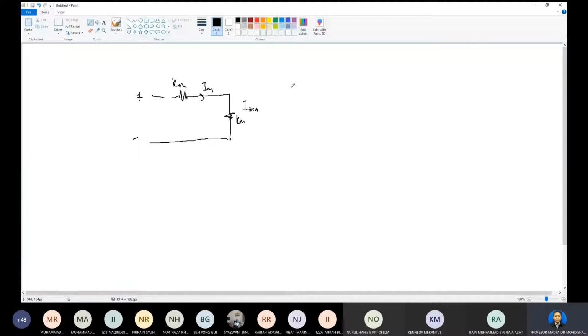So we are given IM equals 100 microampere, RM equals 1 kilo ohm, and the range equals 100, full scale deflection. First we have to calculate the sensitivity. The formula to calculate the resistor R shunt here: R = S multiplied by range, minus RM.